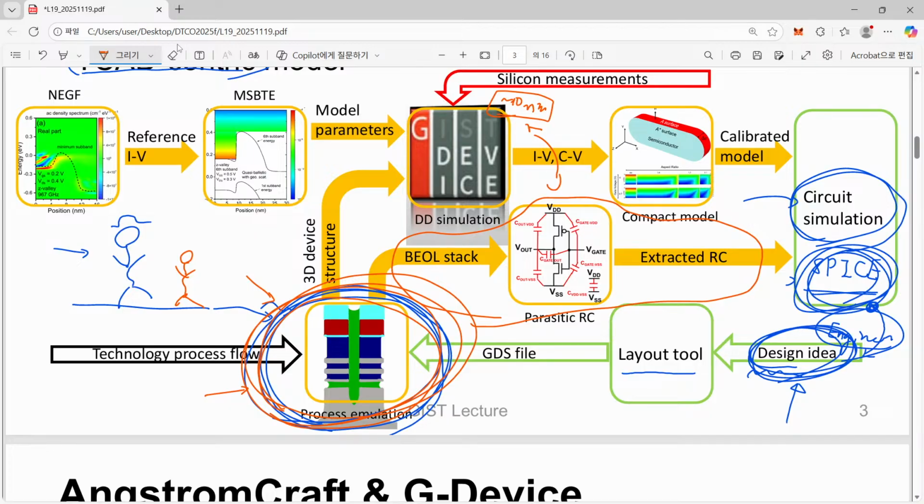In order to switch on and switch off, we usually rely on the inversion phenomena. And in order to do the inversion phenomena efficiently, we have to have a very clean interface and suitable work function and very high channel mobility, and also we have to have a relatively low resistance for contacts. They are all important and they are all quite cross correlated. So therefore this part is more governed by advanced physics, and that is relatively difficult.